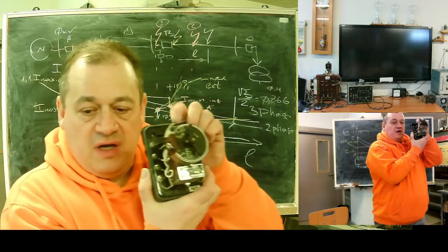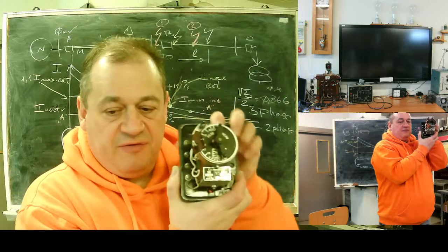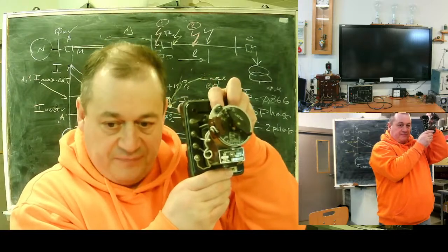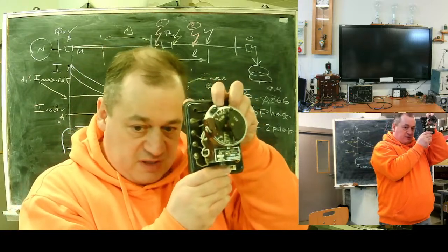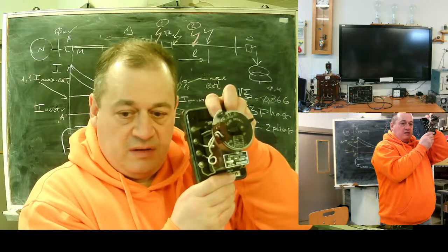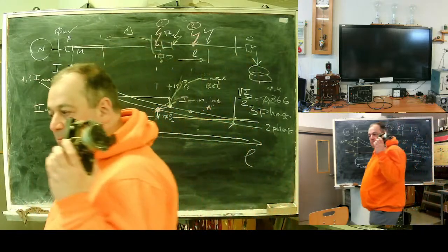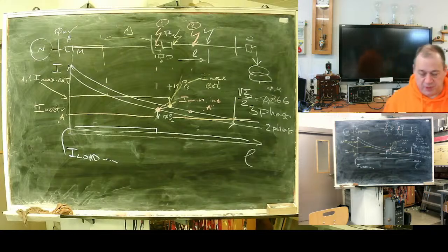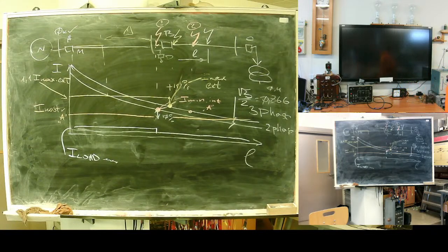And what if the input signal disappears before the output signal is sent? What happens? You see, it returns to its previous condition. The input binary signal should be present for all 2.5 seconds, the whole delay time. If it disappears or is cleared before the output signal is sent, the delay function returns to its original, zero state. Yeah? Now, how will it work?